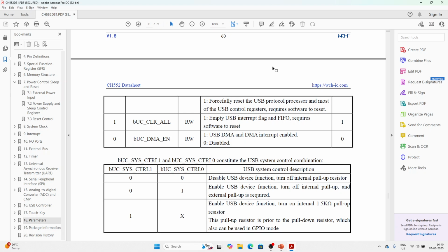If we are using 5 volts or anything above 3.6 volts, VCC becomes anything above 3.6 volts up to 5 volts, and the internal LDO kicks in, and the 3.3 volt pin gets 3.3 volts internally from the microcontroller itself, and no need of external LDO.